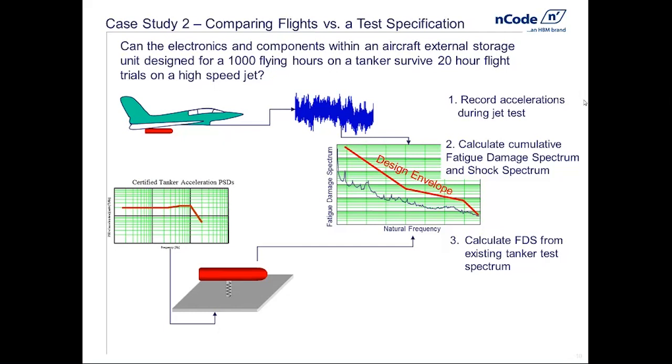So we know for a fact that this device passes this random vibration spec for, say, 30 hours or whatever the service life was. So we know that it can pass one test. That's the lower left corner, the existing shaker profile. The question is now, is the new vibration data up at the top more or less severe than that?